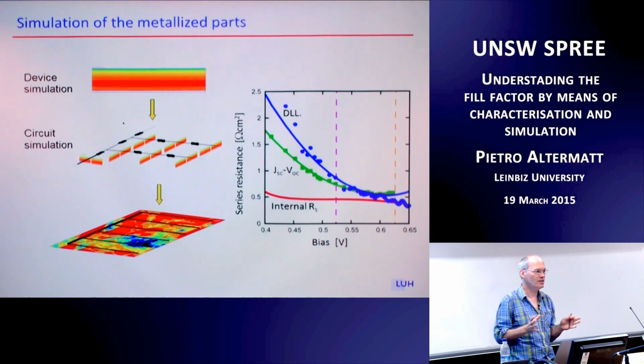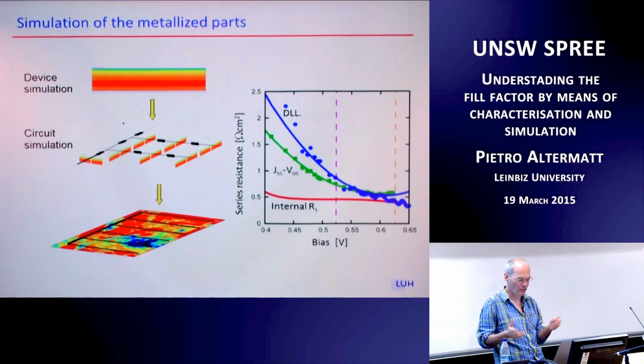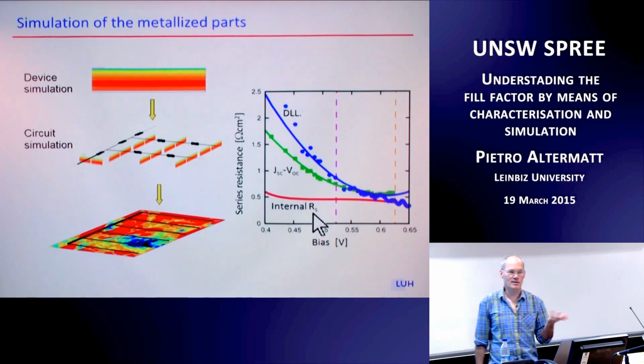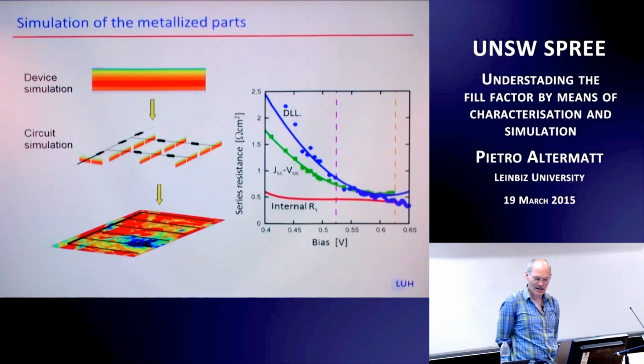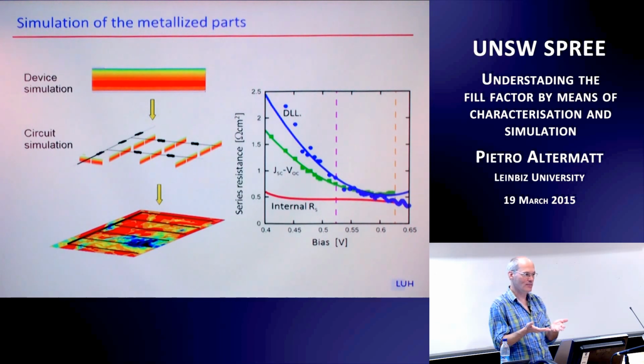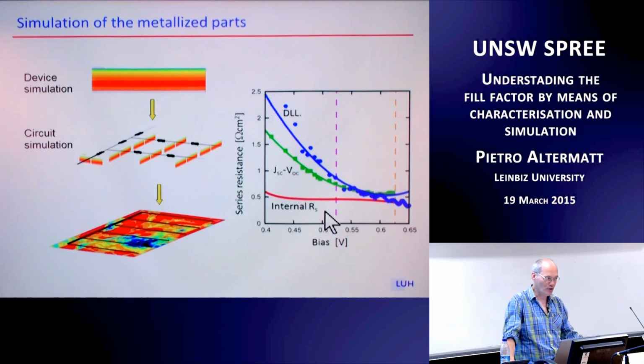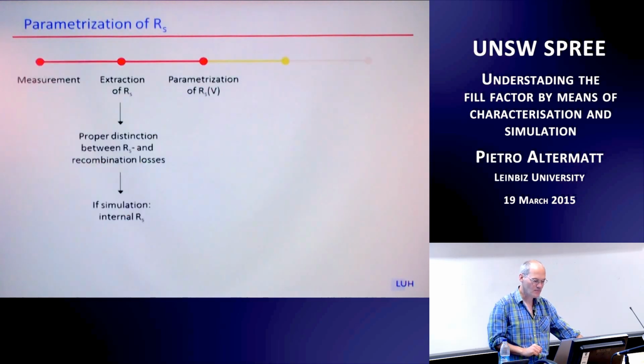It's not like recombination. It just depends on your dopant profile, and you need to get the voltage right. And this is what you see here as internal resistance. I model that, and then I actually know what's internal resistance. That means the semiconductor part, the contact resistance part, and what's the metallization. The metallization is RS on top of here, and RS below here is the internal one.